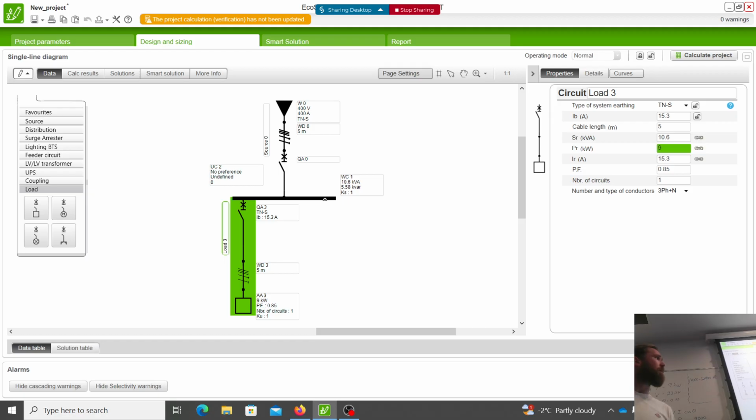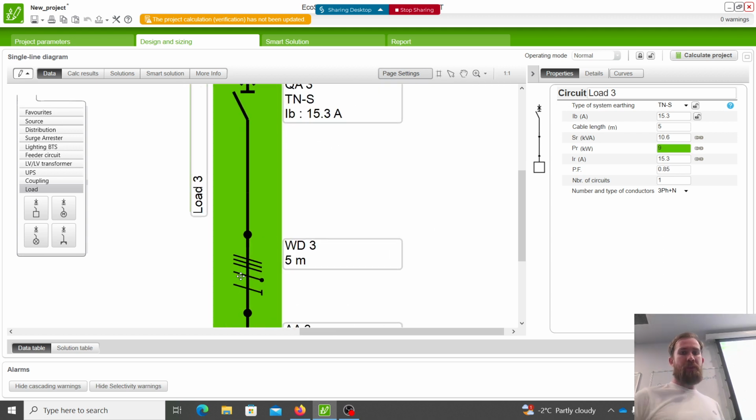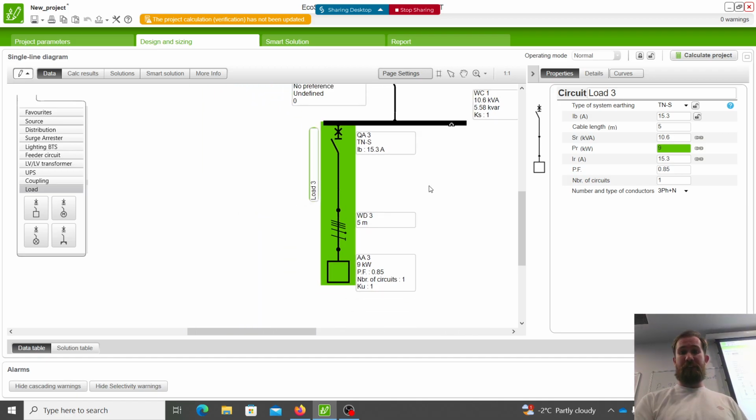Okay. Where do you see that? Yeah. It defaults to a 3-phase load. So if you're looking here, you'll see it has 3-phase and neutral as default. If you didn't spot that, you could also look at the diagram. It's defaulting to a 3-phase, neutral and earth cable. So already, if you're reading the diagram, you'll have the same information.